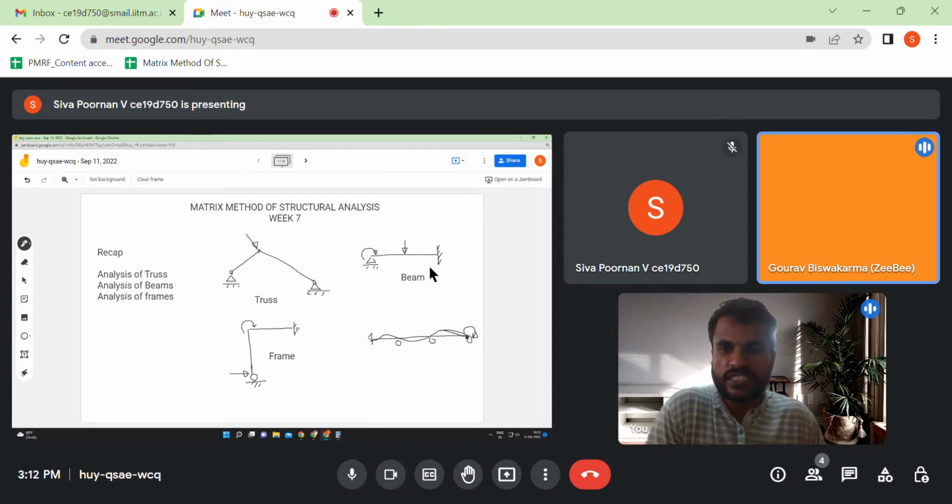Those are the kinds of checks. In a real structure, there are a number of loads. Usually in industry there are 16 basic load cases: wind, earthquake, equipment load, dead load, live load, all of those comprise the 16 load cases. So all 16 load cases should be individually, statically in equilibrium.